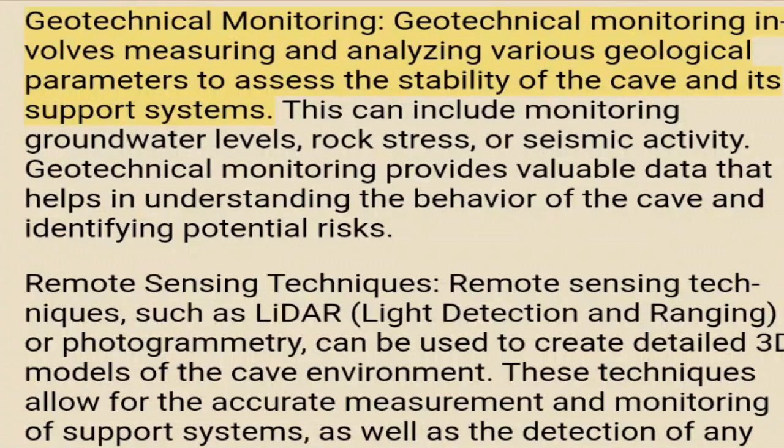Geotechnical monitoring. Geotechnical monitoring involves measuring and analyzing various geological parameters to assess the stability of the cave and its support systems. This can include monitoring groundwater levels, rock stress, or seismic activity. Geotechnical monitoring provides valuable data that helps in understanding the behavior of the cave and identifying potential risks.